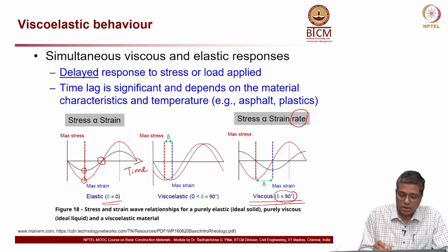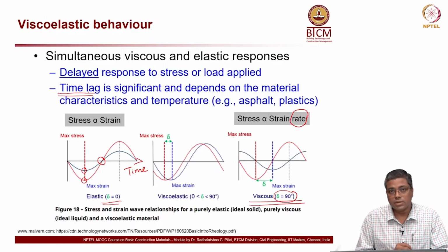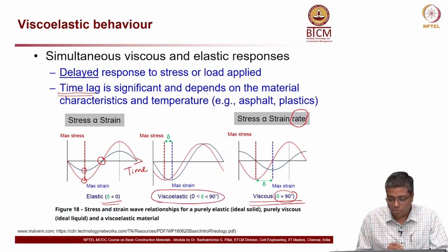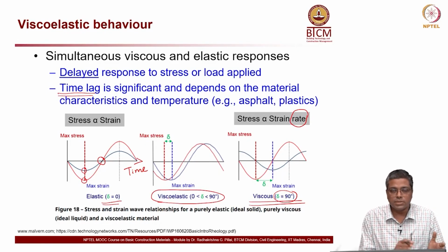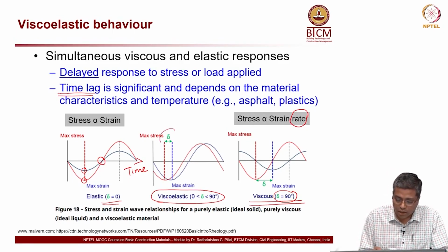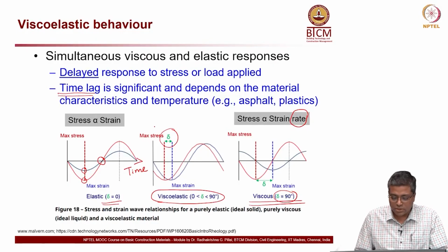And this time lag actually depends on the material characteristics and temperature. Now, if you look at the viscoelastic behavior, there is also definitely a time lag, but that is in between the pure elastic case and the pure viscous case. So, you have a time lag or phase difference, indicated by delta there.